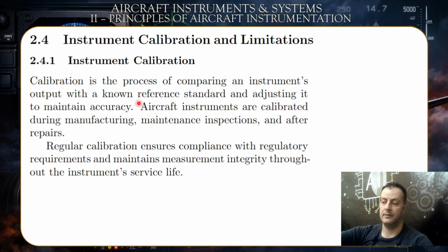We set the air pressure of the static, compartmentalized air within the altimeter. We set it to the air pressure on the ground when the aircraft is still at the airport. That would be the reference pressure, and that would be the 0 meter height of the airplane. Based on that reference, when the aircraft climbs in the air, it would be able to accurately measure its height in reference to this static pressure, which is the pressure of the air when the height was 0.